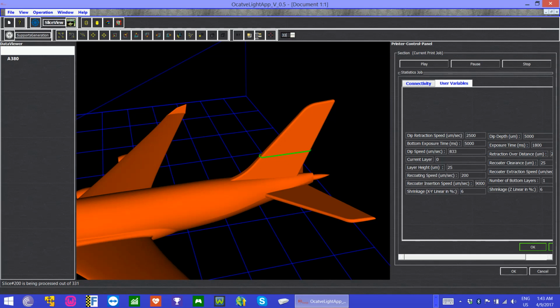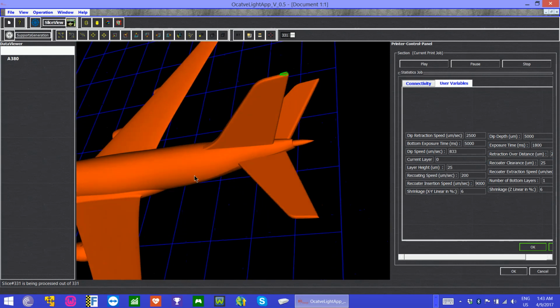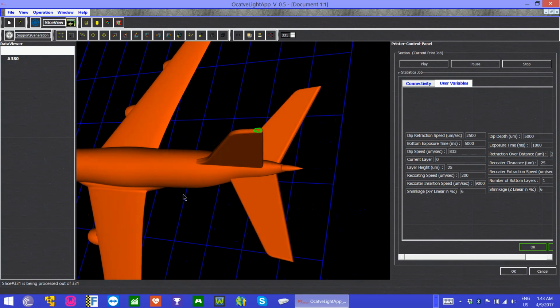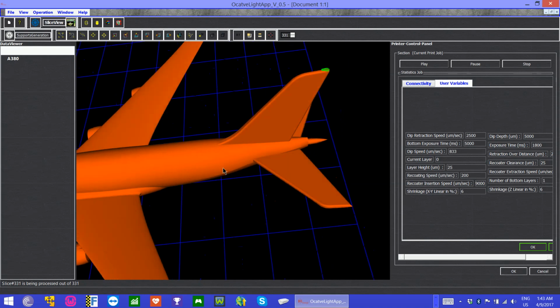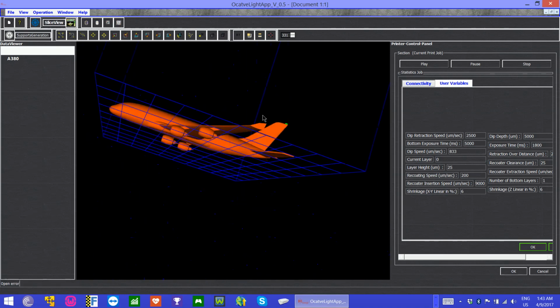If you give 331, the last slice is the tip section of the radar vertical stabilizer. It is under selected mode. You deselect it, and the color will be retained.